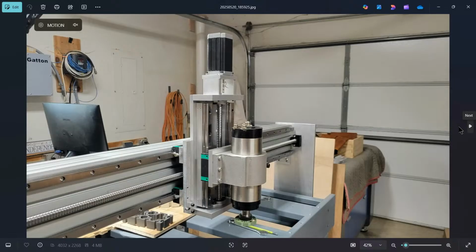And right now, for the initial settings, I don't have everything turned up power wise like it should be. I'm running 50 volts on those NEMA 34 motors, but I can go on the drivers up to 6 amps, and I really have them set at about half of that. Well, a little over 3, I think, right now, until I get everything broke in.